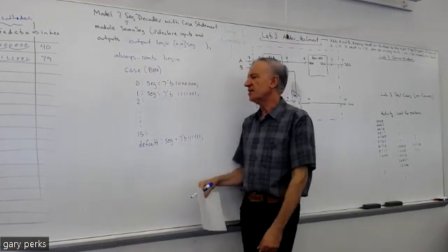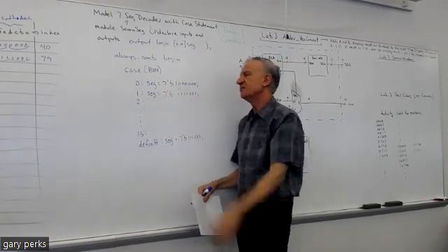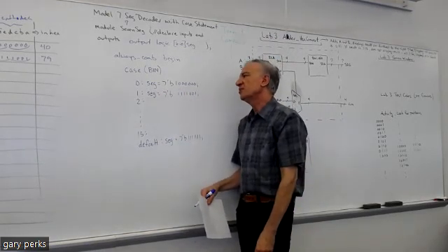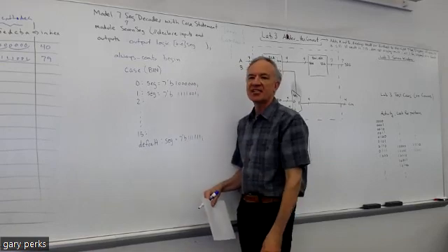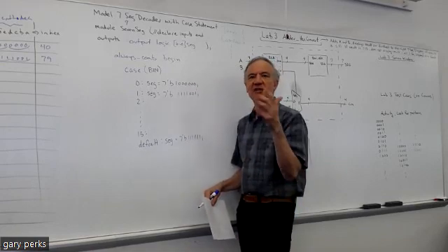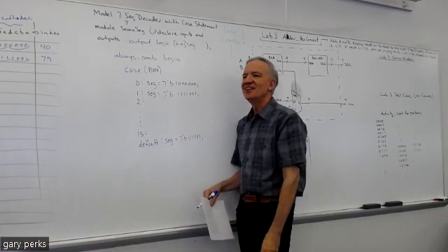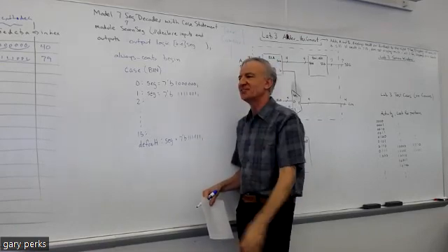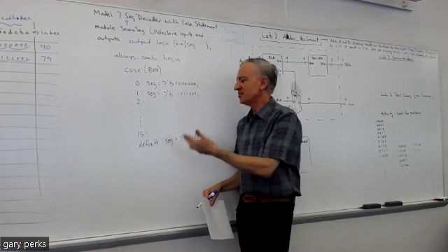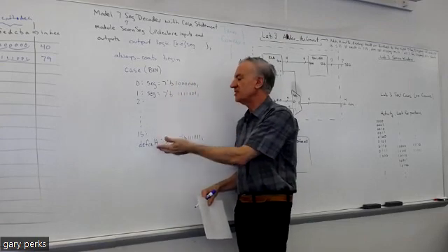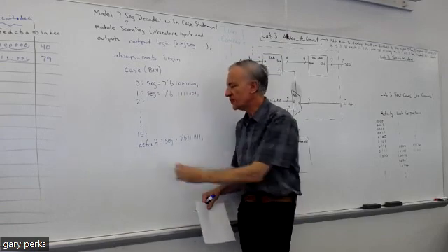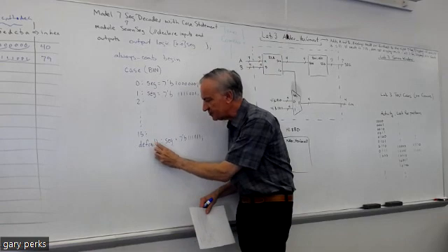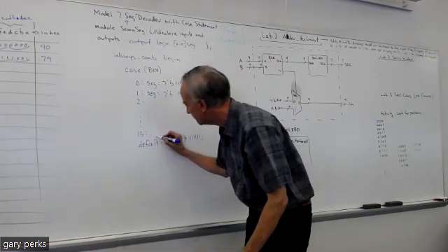Okay, and the default is there in case something happens where, for some reason, a real life example would be, say this system was on a satellite or something, and the satellite got blasted by solar flares, and there were photons that changed bits. If you didn't have the default, it would get hung up somewhere in the case statement. So it's there for a catastrophic case.